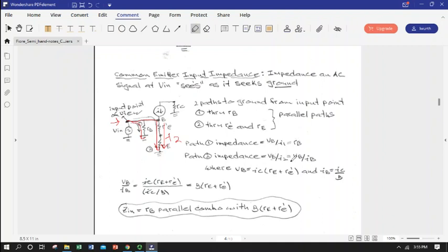So we've kind of already looked at that when we defined the voltage of V sub B in terms of the collector current. So we know that V sub B, if we're looking at this ground, is just the emitter current, which is pretty much the collector current, times these two series resistors. So we can build our real impedance to ground by using that definition. We can plug in our values here.